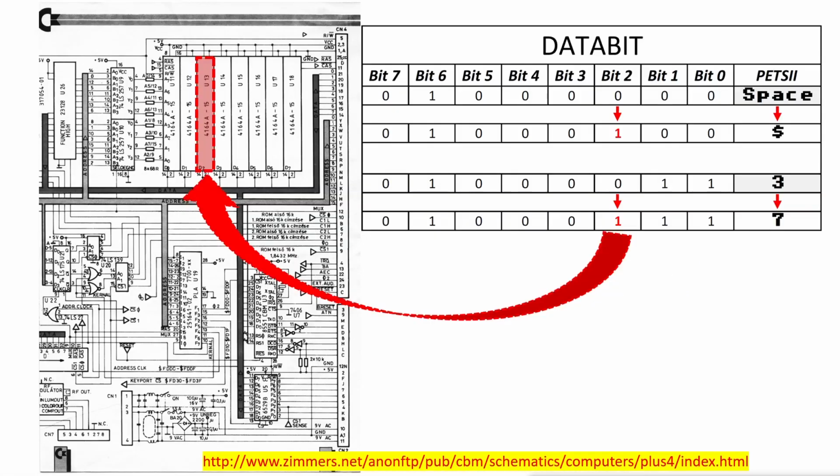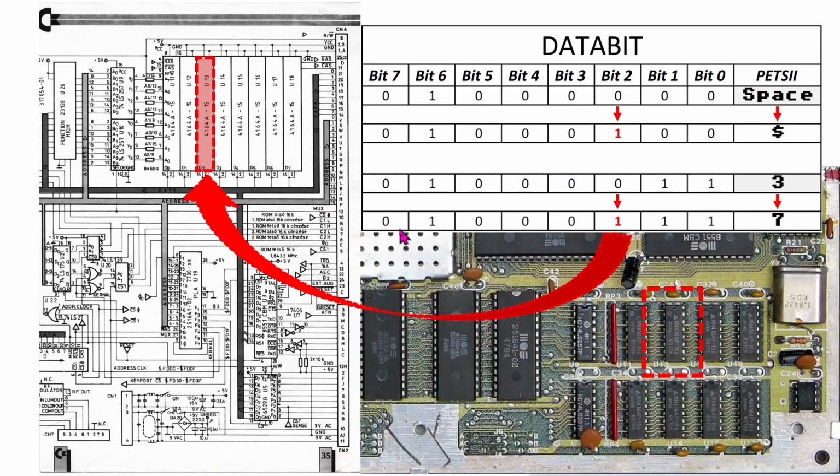And if we analyze this a bit further down to the schematics, we saw that it was bit 2, and bit 2 is here stated. This is D0, D1 and D2. So it's U13 that is the culprit if it is a memory chip that is faulty. And U13 is placed so on the board, and it's quite easy to desolder this on the Plus 4.